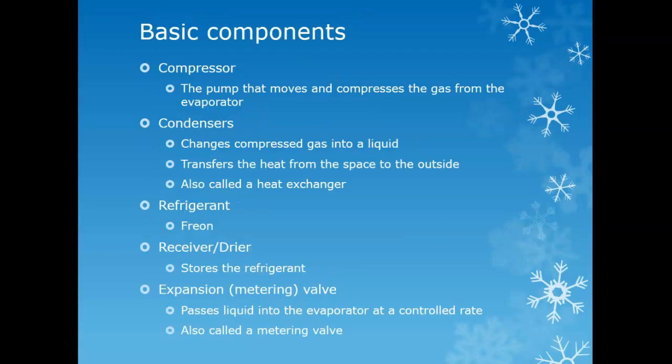Basic components, you have a compressor. Now we know what a compressor is, right? It takes outside air and squeezes it down, right? Well, in this, it does the same thing. The pump compresses the gas from the evaporator. So it's taking all that gas and bringing it back together, right?